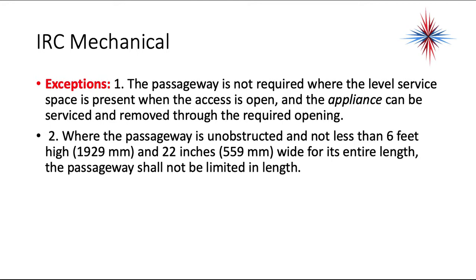There are a few exceptions again. A passageway is not required where the level service space is present when the access is opened and the appliance can be serviced and removed through the required opening. In other words, if I open the access to the crawl space and could service it right there, a passageway is not required. The other way is when the passageway is unobstructed and not less than 6 feet high and 22 inches wide for its entire length.